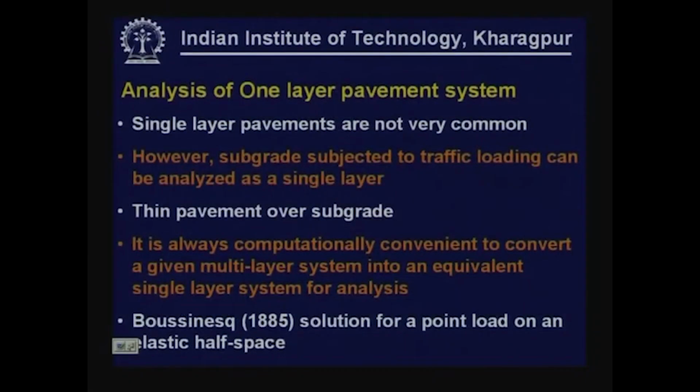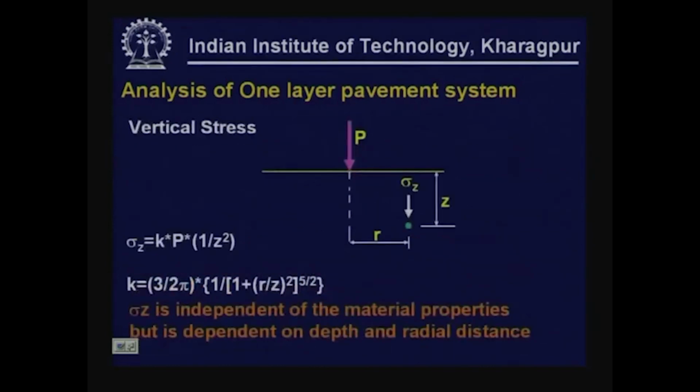Boussinesq, as you might have learnt in soil mechanics subjects, was the first to give a solution for a point load on an elastic half space. Elastic half space is a single layer system. The Boussinesq analysis considers a concentrated load P applied at the surface.